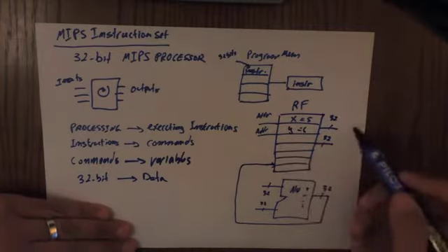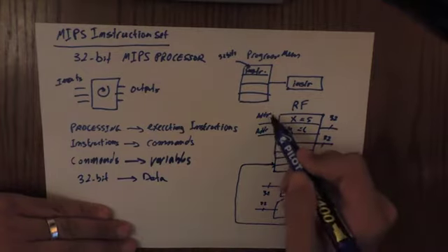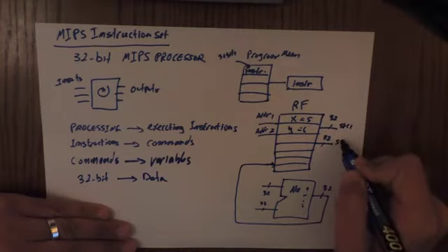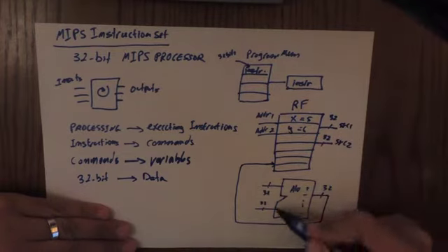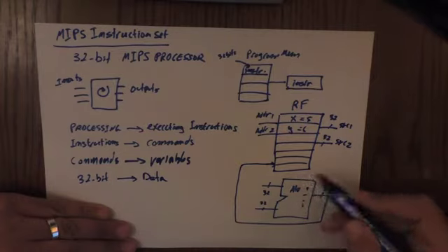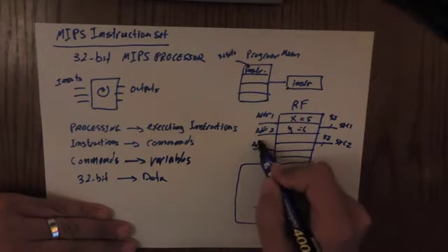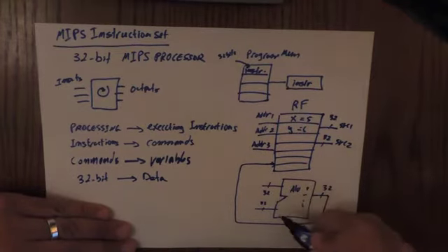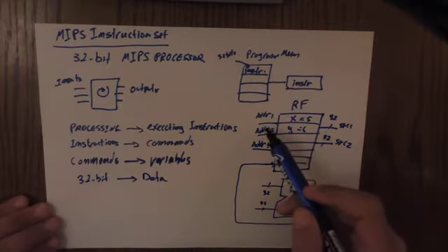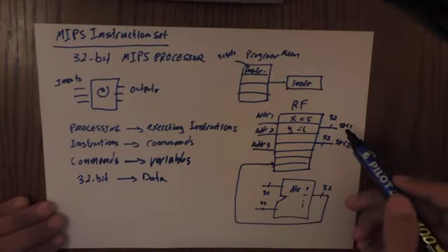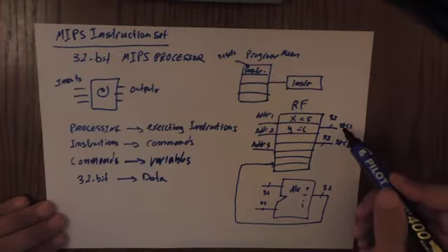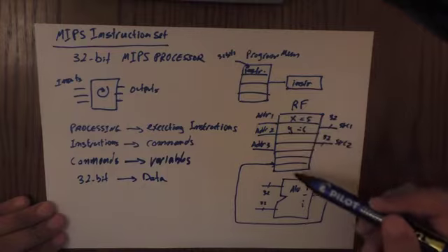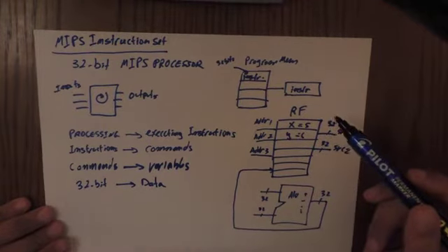So these two addresses, let's call them address 1 and address 2, will get us source 1 and source 2, and of course I want an address to save my data. So I need a third address, address 3, which will save the 32-bit data. Of course, the size of the address is independent of the size of the data bus, because the address will help us compute the number of locations, or the size of the memory.